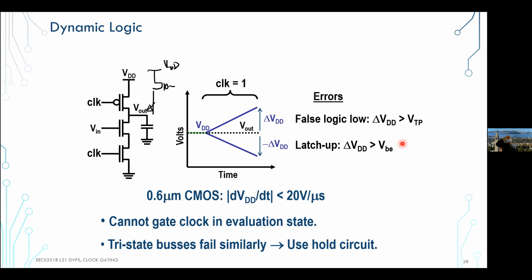One thing that's a little bit tricky, luckily not too big of a deal right now because we don't use these things too much: in the first half of the 2000s, people still used dynamic circuits up till 2004-5 in certain very high performance parts of the ALUs. So if you start doing these voltage scaling things, you need to be aware of what's happening, because your dynamic logic may be remembering a certain voltage value that came from a previous supply setting on that transition, right? And then it may drive that gate either into a fail mode because it can't drive the other gate, it's underdriven, or into a complete fail, like a latch up, because it now overshoots the supply compared to the previous one, right?